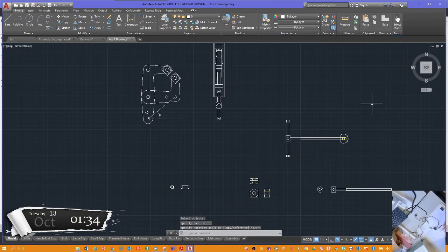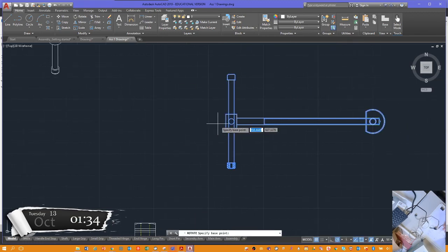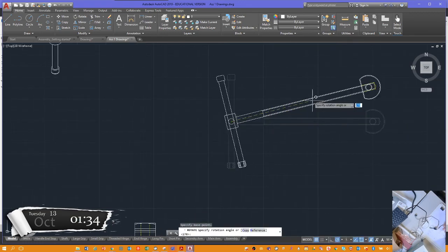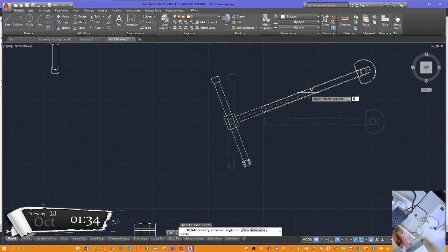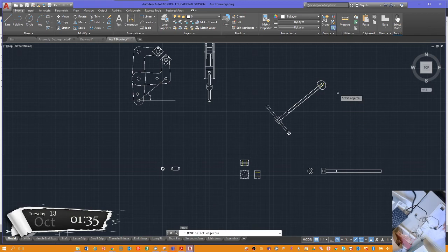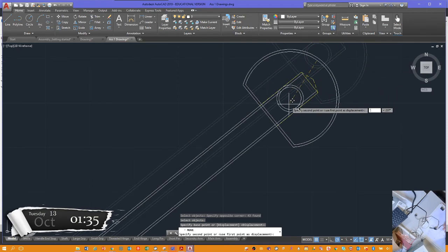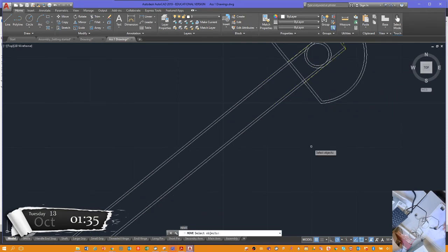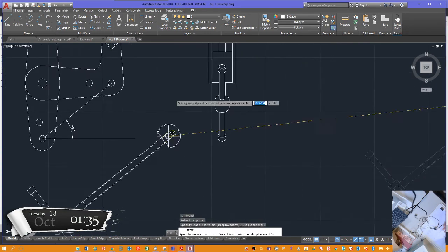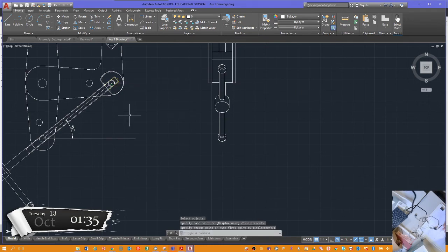Right, let's make this a bit easier. Well, for my poor adult brain anyway, I can't think and cast at the same time. Let's move it around there, and let's move it up by 39 degrees and see if that gets us in the right direction. So move that, let's select the lot again. I'm going to move that from, zoom in a bit, center point of that, oops daisy, didn't get that right, did I? M, P for previous, right click, center point of that circle, there we go. Put that there, spot on, excellent.